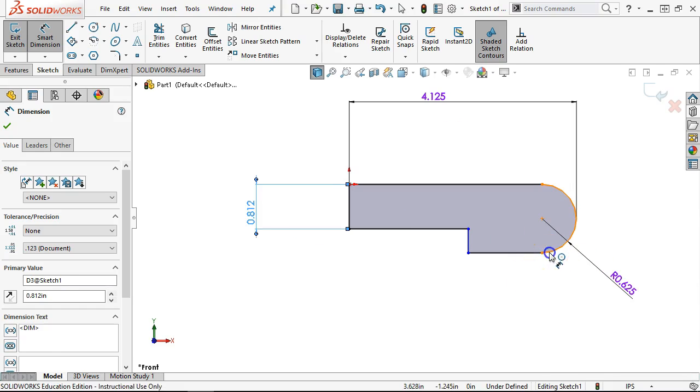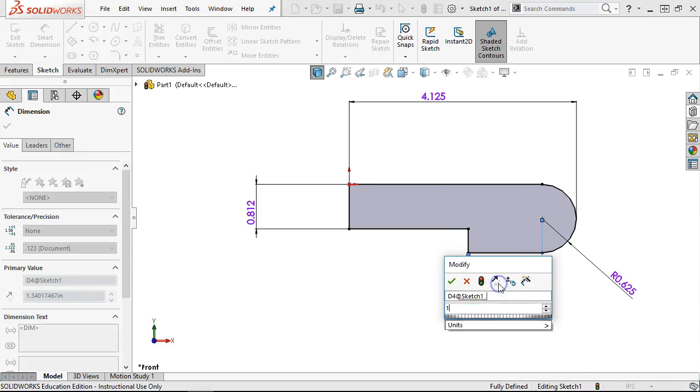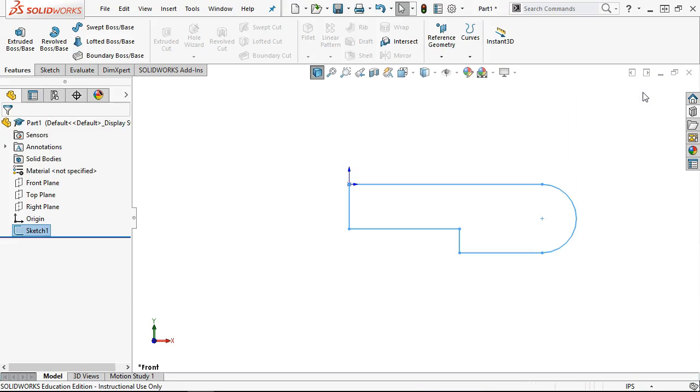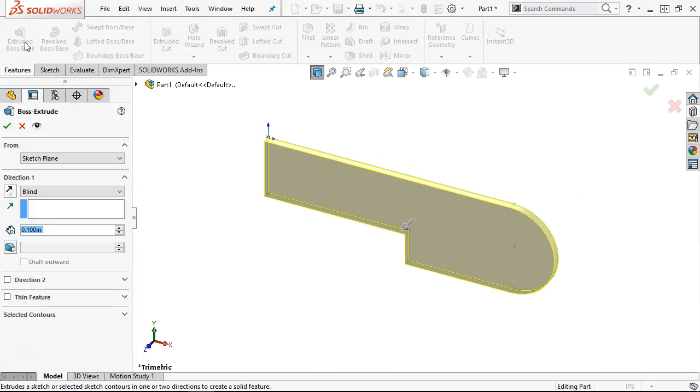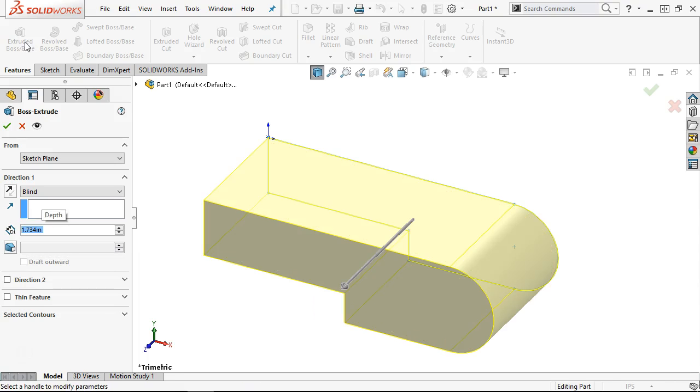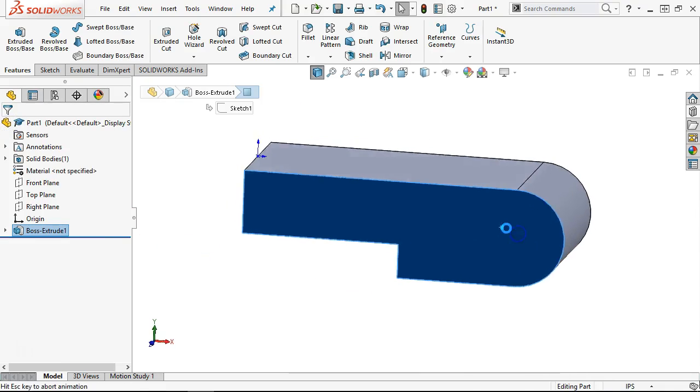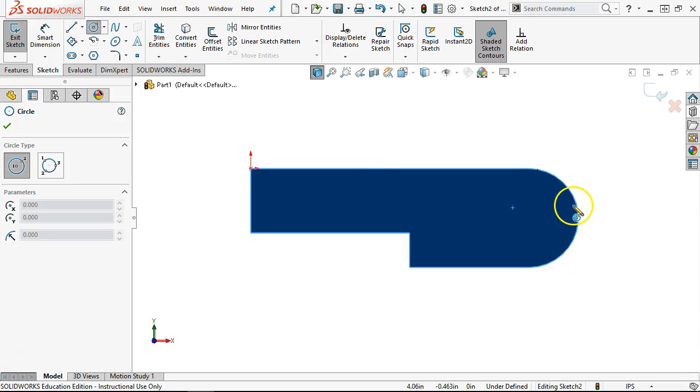And then a dimension 1.5 from the center, so I'll still select the circle just in case, but 1.5 from the center of the arc back. The through hole, that comes out to be a reamed, another tight tolerance, 626 to 628. Oh, I jumped out of it. Let's go ahead and take it out to the 1.734. I'm going to go ahead with midplane. I'm not entirely sure that I need it to be midplane, but we'll get it into position for it. We're going to hover over the edge until the center point shows up.